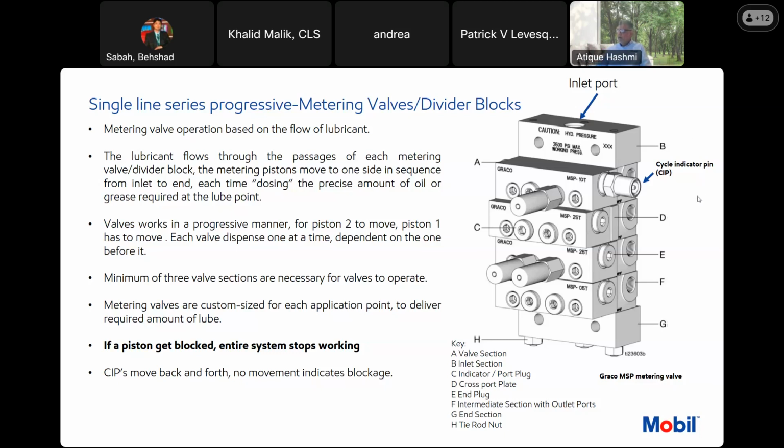So rather than installing all 25T, I would assign a smaller one, like 5T, for the bearing which requires the lowest amount of grease. And I would install 25T or 40T, where 40T is the highest, for a bearing with the highest requirement per hour.